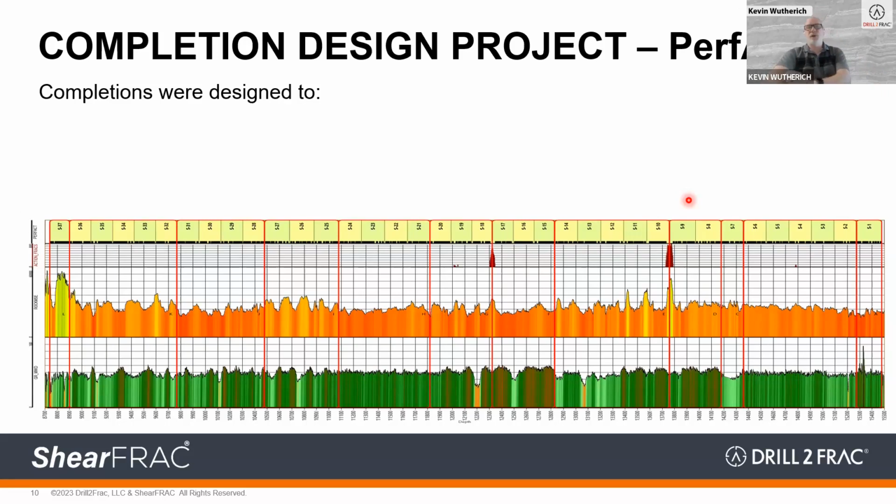So now that we have this information, we know what the rock strength is along the wellbore. This is the gamma ray, this is the rock strength, and here is the location of some of those depleted areas, right? So the first thing we do, if we're trying to design a completion to take this information into account, is this: we don't like making wholesale changes to designs, but what we did is say, okay, knowing this, how can you adapt your current completion to take into account these localized changes in heterogeneity in the presence of pre-existing fractures?